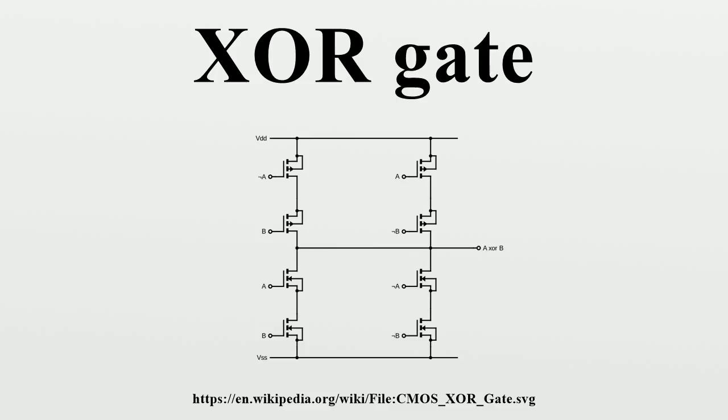In this example, the best match occurs when the target sequence is offset by 1 bit and all 5 bits match. When offset by 5 bits, the sequence exactly matches its inverse. By looking at the difference between the number of 1s and 0s that come out of the bank of XOR gates, it is easy to see where the sequence occurs and whether or not it is inverted. Longer sequences are easier to detect than short sequences.